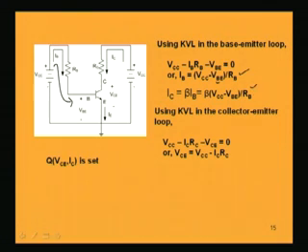So, this is your DC value of collector current. Again using Kirchhoff's voltage law in the output circuit, that is in the collector to emitter loop, if I consider this loop starting from this point and ending again here, the algebraic summation of all the voltage drops is 0 in a loop. Applying that, I get VCC minus ICRC minus VCE is equal to 0.